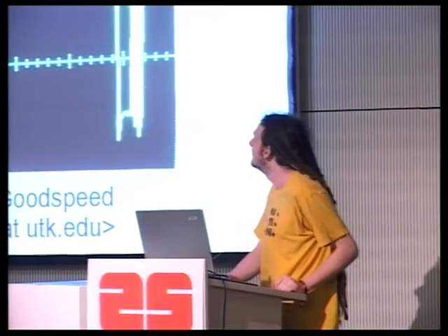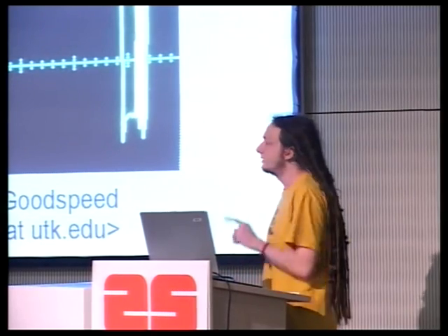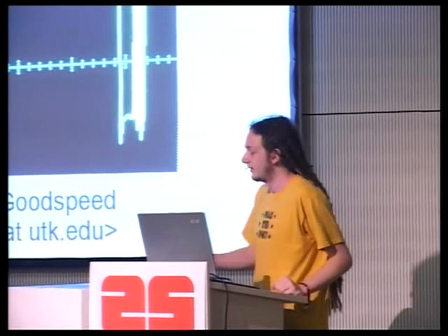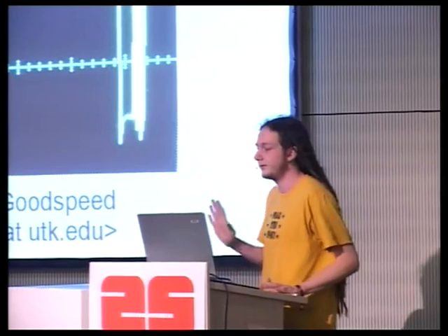Okay, that's better. So in part 1, I described a theoretical attack against the msp430 microcontroller, which is a 16-bit chip with a computer contained entirely within it. You give it stable power, and you can put a program into the chip and it runs it, just as a larger computer would, except that it's embedded. You can throw it on a board and such. Since then, I've actually gotten it to work in hardware. I've broken a chip with it, and I've built this little device for attacking the chip. Some versions are vulnerable, some versions aren't.